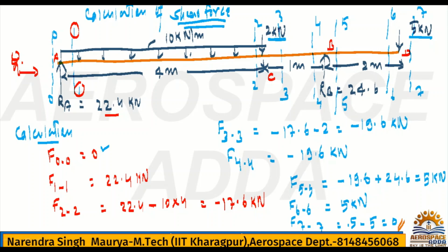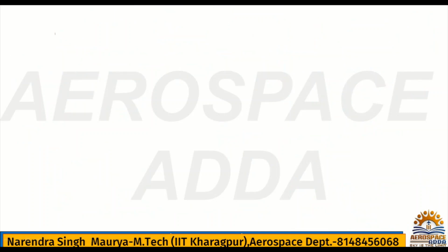So once you have got the shear force, now we have to draw it. As I told you, once you are going to draw the beam SFD, you have to draw the beam exactly, and then extend all the force points downward, and then nicely draw. So there will not be any mistake. Otherwise, chances are there you may commit a mistake. So better first we'll draw the beam again. Now this is the beam here, see,